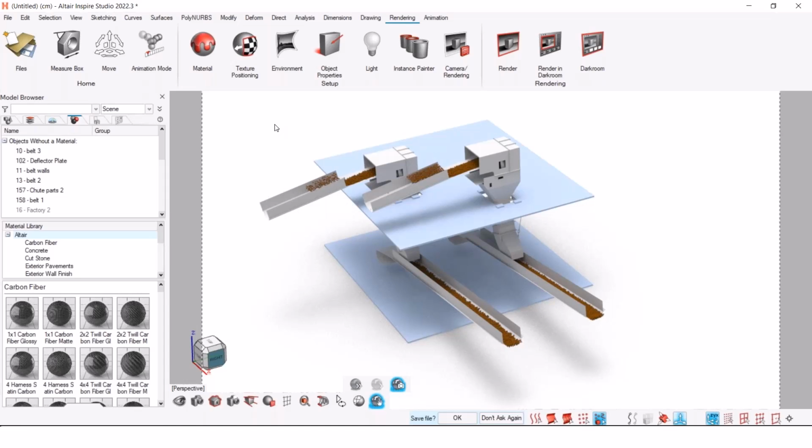I'm not the biggest expert on how the code works, but I can tell you from my experience. When it comes to geometry complexity, if EDEM can handle it, generally speaking, Inspire Studio can as well. Once it's imported, it will be imported as a mesh based on the information it was getting from EDEM. The good thing of getting the import from EDEM, by the way, good to touch on this now, is that anything that comes from the EDEM time steps is going to update the position, orientation, and everything else as it would in the EDEM simulation. So any geometries that are moving are going to move like they were moving in the EDEM simulation. Any particles are going to move like they were moving in the EDEM simulation.